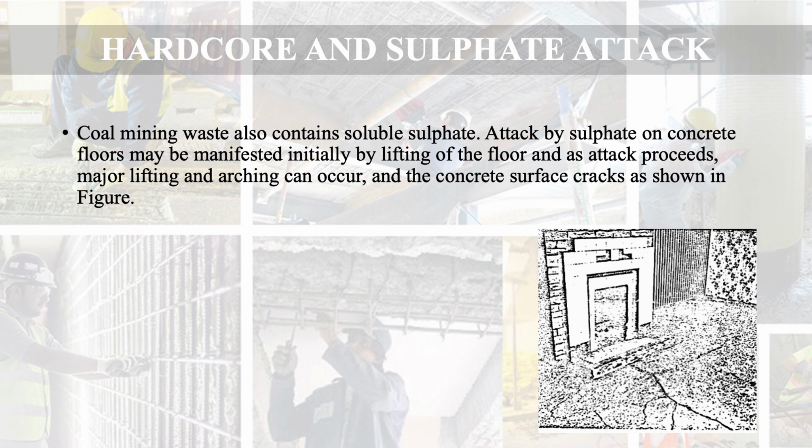Attack by sulfate on concrete floors may be manifested initially by lifting of the floor, and as attack proceeds, major lifting and arching can occur and the concrete surface cracks, as you see in this figure. Here you see the cracks on the floor. These cracks are quite wide and long also.